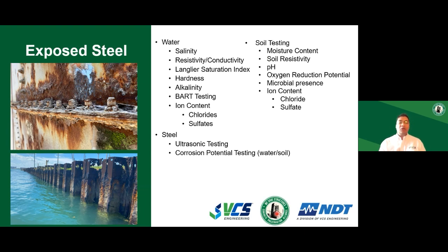When it comes to waterfront structures, you have a series of tests you can run to see if your water is corrosive or not. One way to do it is just check for the salinity and the conductivity of the water, and it will tell you if the water is highly saline, how much chlorides or sulfate it has. You need to run an ion concentration test. You need to also test for hardness and alkalinity, especially if your water is fresh water.